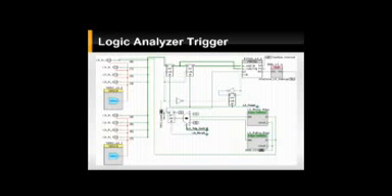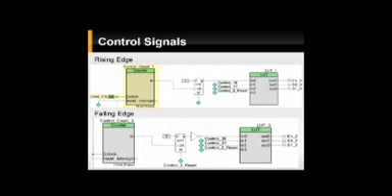The trigger for the logic analyzer only exists on channel 0 and works similar to the oscilloscope. Once triggered, the bottom left flip-flop goes high, which enables the FIFO. Unless enabled, the FIFO will not store data. The control signals use a counter, which on every clock cycle increments the count. Once the count reaches a specified value, a pulse is generated, which activates the flip-flop and sends a high digital signal to a lookup table.